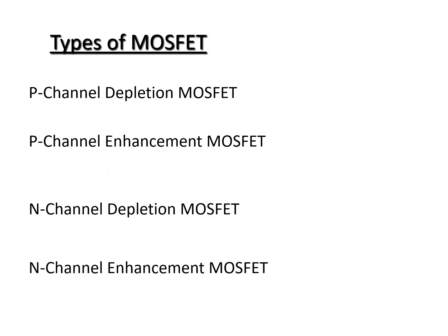Now, different types of MOSFET. MOSFET works in two modes, depletion mode and enhancement mode. In depletion mode, the transistor requires the gate source voltage to switch the device off, and the depletion mode of MOSFET is equivalent to a normally closed switch. In enhancement mode, the transistor requires a gate source voltage to switch the device on. The enhancement mode of MOSFET is equivalent to a normally open switch.